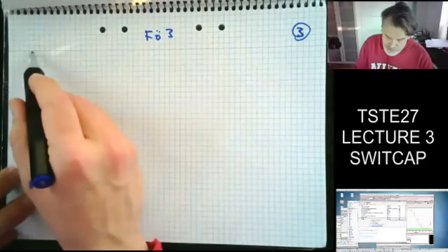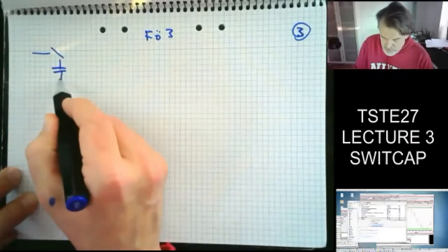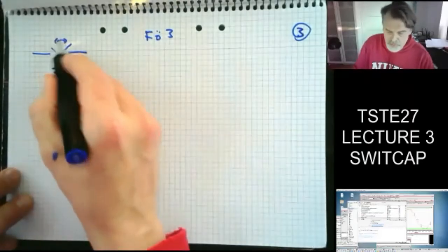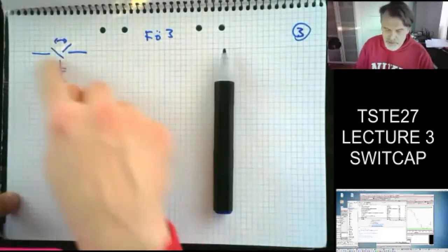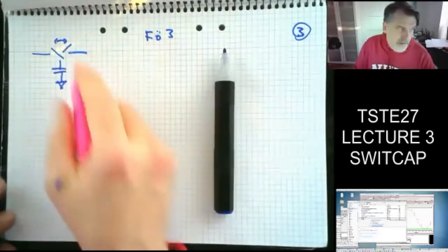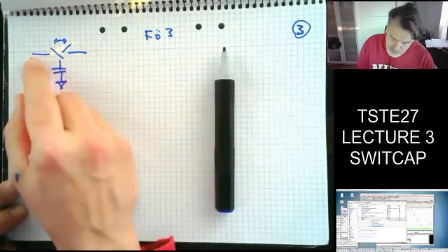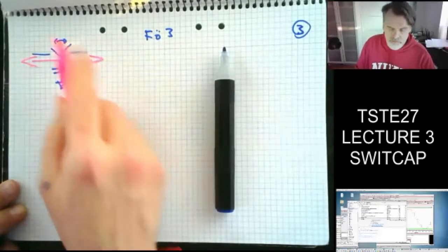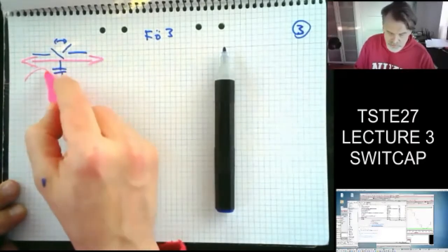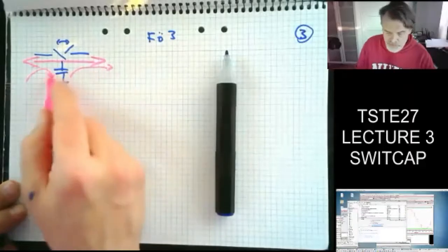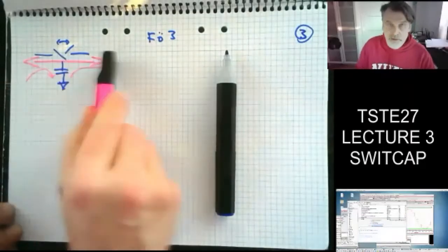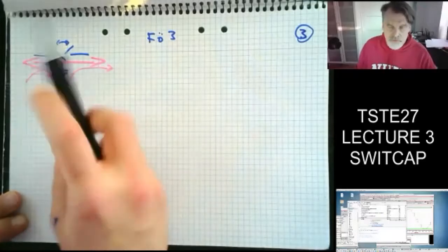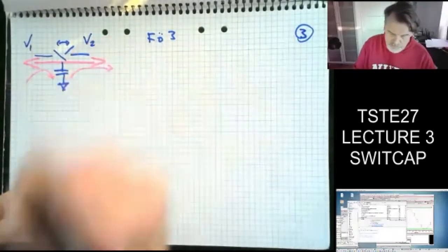All right, so let's look at the net transportation of charge from the input to the output. So I imagine that I have my capacitor like this, and then I have the possibility to switch this back and forth, dependent on what's connected on the other sides, etc. But I don't care at the moment. I just say that I have a net charge going back and forth here. So I induce charge on the capacitor. I might move them out. I might move them back, etc. But at least I can argue that there is a net transportation of charge from Vin to V2.